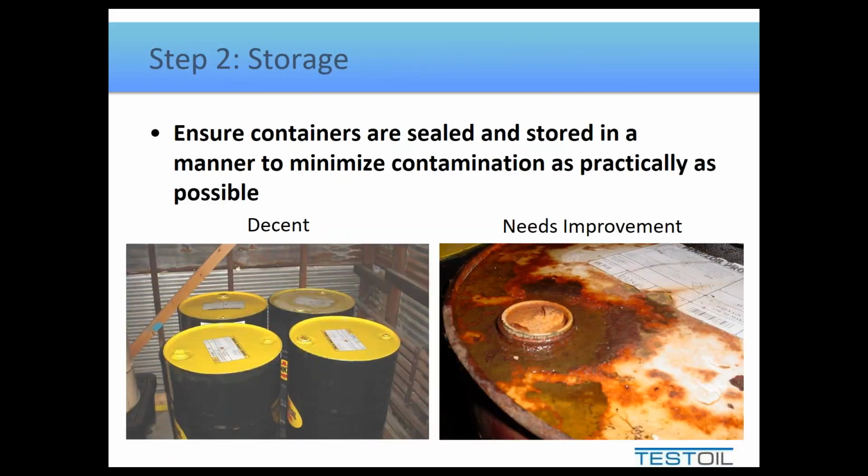How do we store a lubricant so that it doesn't get any dirtier than how we received it? And are there any things we can do to clean it up? So within step two, we always need to look at how we store it and where we store it. Ideally, it'd be nice to store everything inside. That helps prevent a fair amount of contamination. But we do need to look at how we store it within that area.